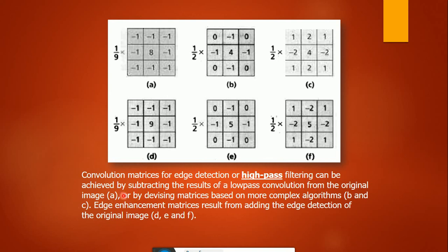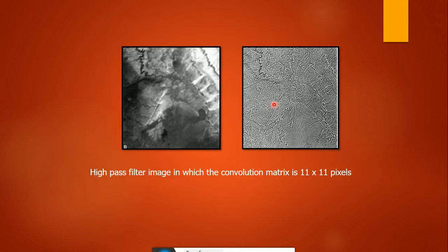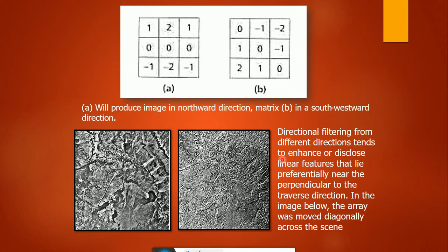Band ratioing. The ratio of two bands removes much of the effect of illumination in the analysis of spectral differences. This is possible because the composition difference between two geological units, say here limestone, which is grey white in RGB 3:1, and red, which is red in RGB 3:1, determines the ratio of any two bands, whereas the illumination determines the magnitude of the digital number DN value received by the satellite. However, in areas with significant haze, the performance of ratioing is much improved by removing the haze produced by Rayleigh scattering in the atmosphere.